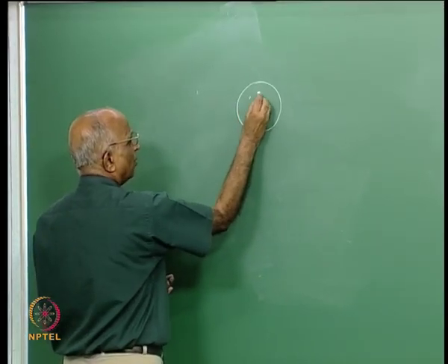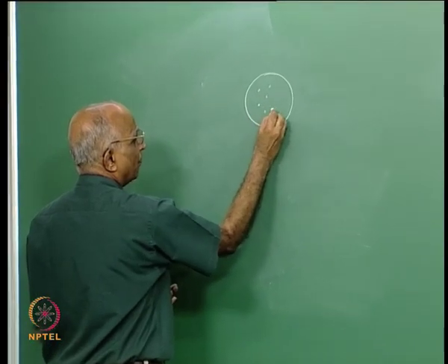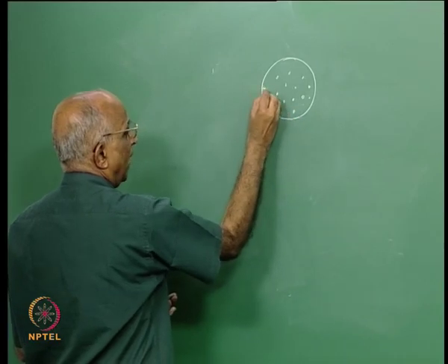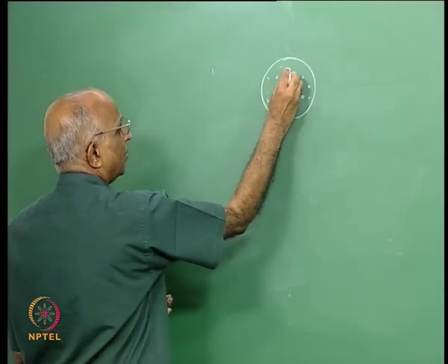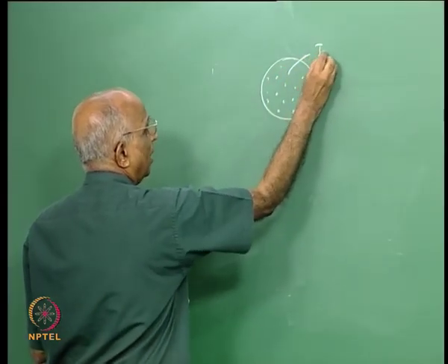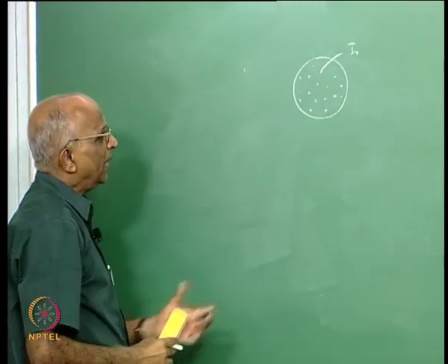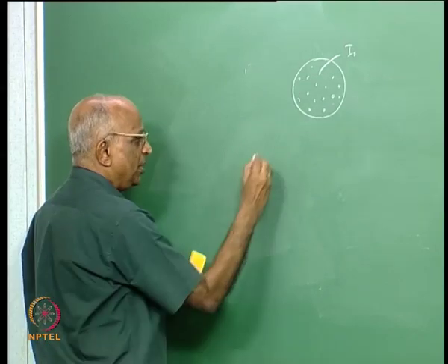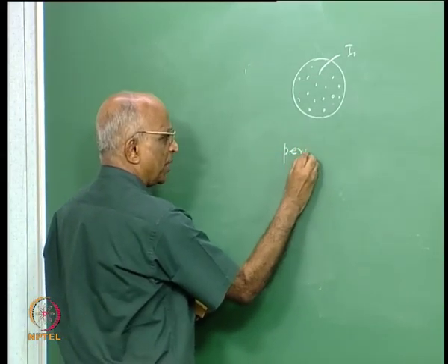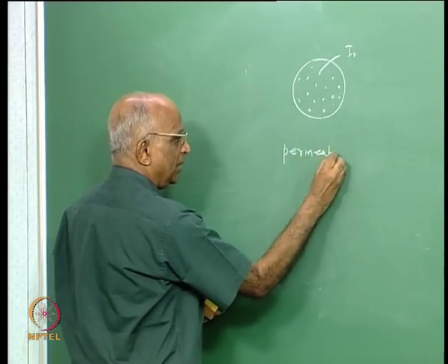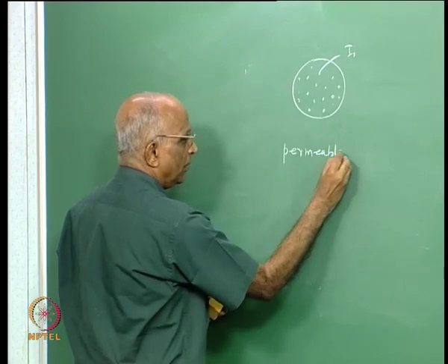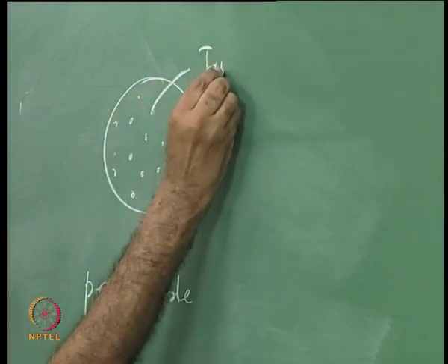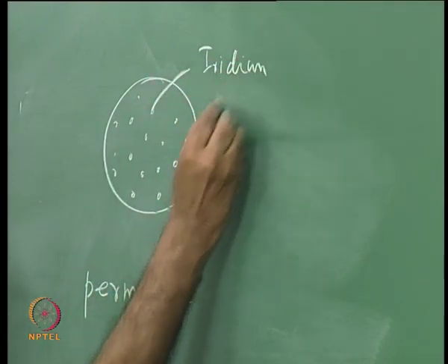In the alumina I have lot of pores or holes, and when I impregnate it, I make sure the iridium is available at all the places, and therefore when hydrazine flows it wets this. That means the alumina is a substance which is permeable to hydrazine. Therefore, permeability is an important parameter. This is iridium in alumina.